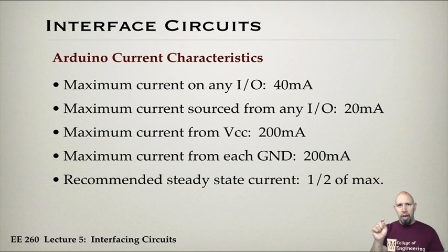For example, if you have digital pin 3 and you set it high, so that it's 5 volts, and you now short that to ground, then you've attached a 0 resistance from the pin to ground, which is going to allow a potentially infinite amount of current. Well, obviously it's not going to be infinite, but it's going to be enough to fry that pin. So obviously that's not a good plan.